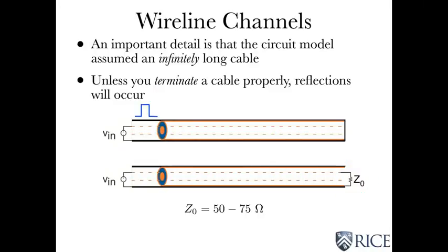It turns out for most coaxial cables, at least that I know of, characteristic impedance is in the range of 50 to 75 ohms. It's not terribly big. You just need to look up the specifications for the coax you use. I've seen some coaxial cables where the characteristic impedance is actually labeled on the surface of the coax, so it's pretty easy to find out what's going on.